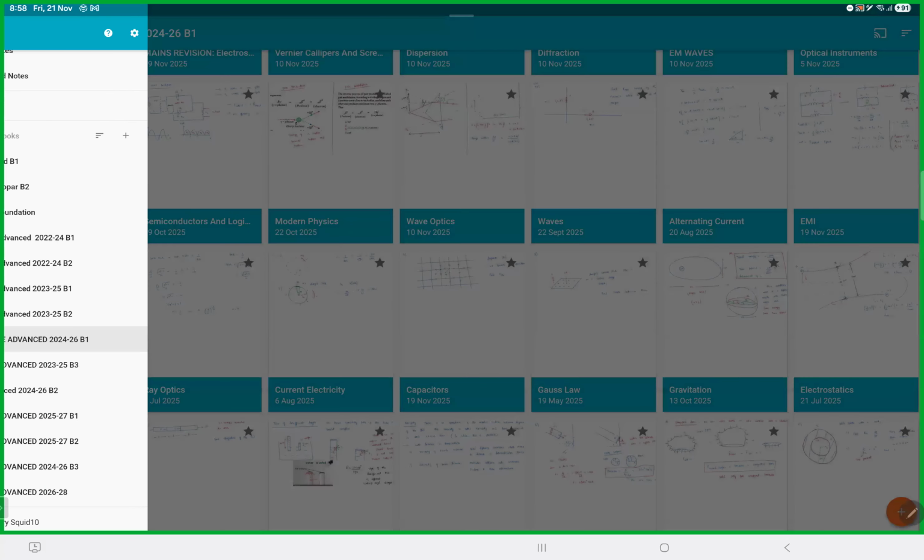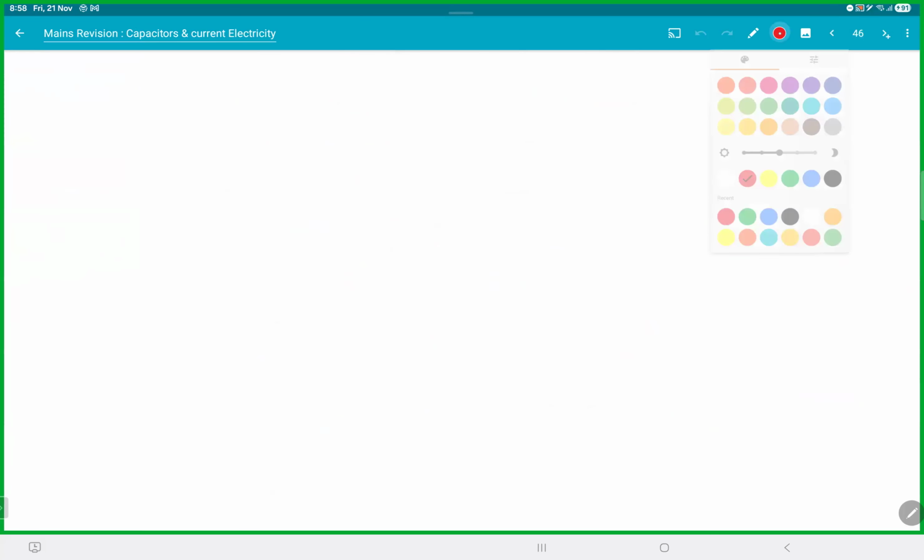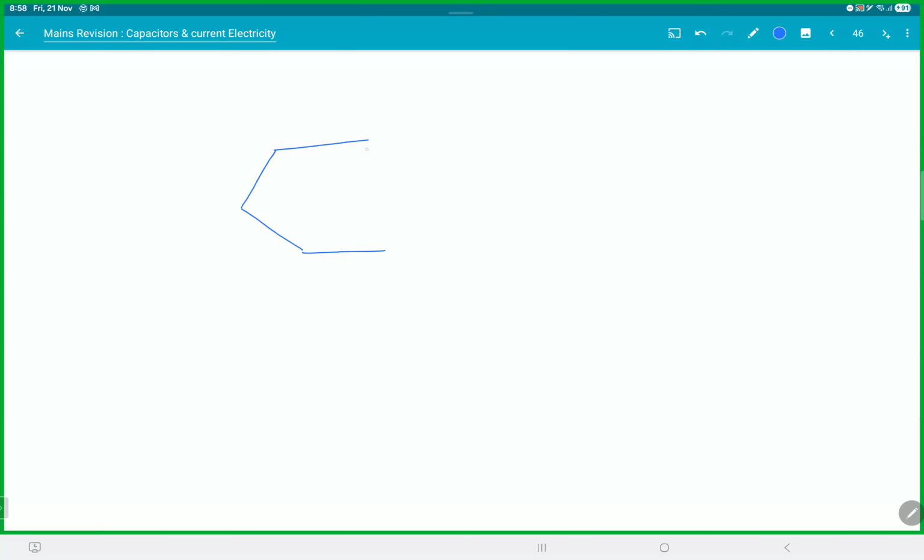So here what we do in this grid, I will not draw everything. I'll just draw one or two circles. So this was A. So what you do, assume current I is flowing through A. By symmetry, we can see the current will split I by 6, I by 6, I by 6, I by 6, and so on. And the current will go till infinity. Current is only going through A.